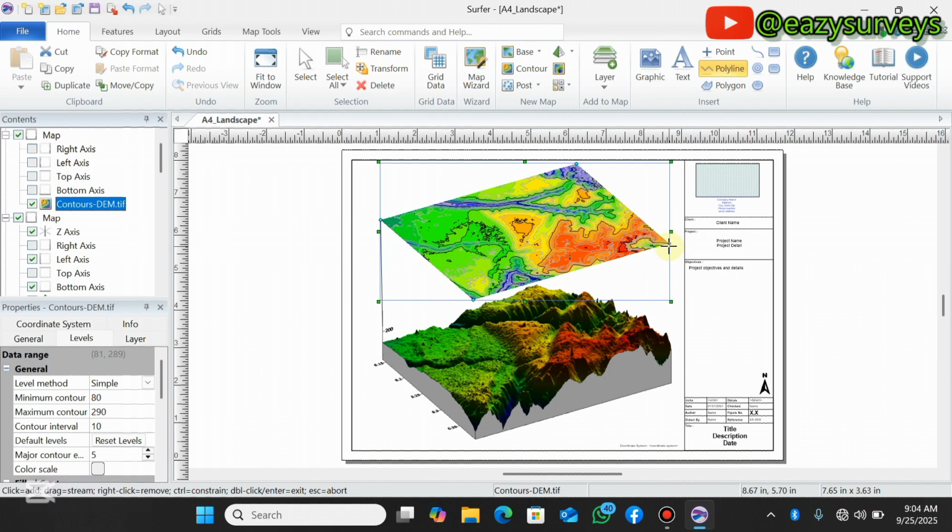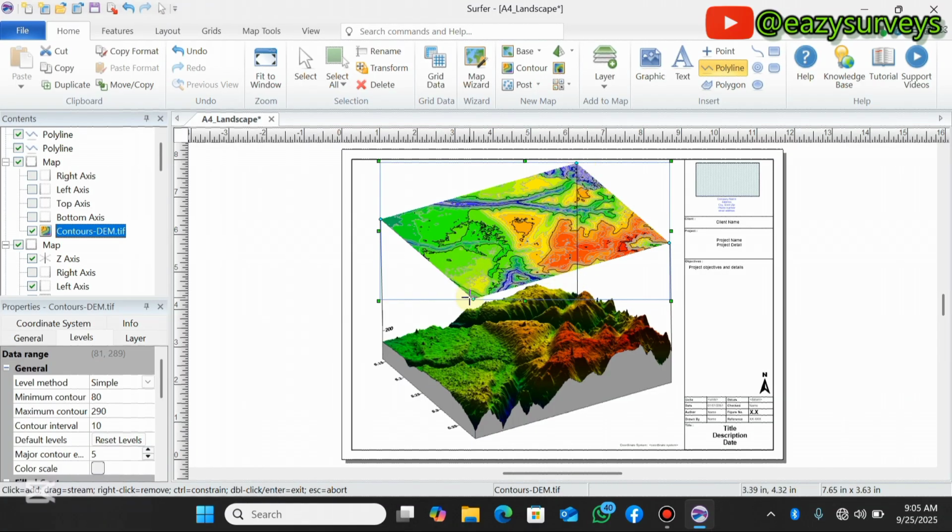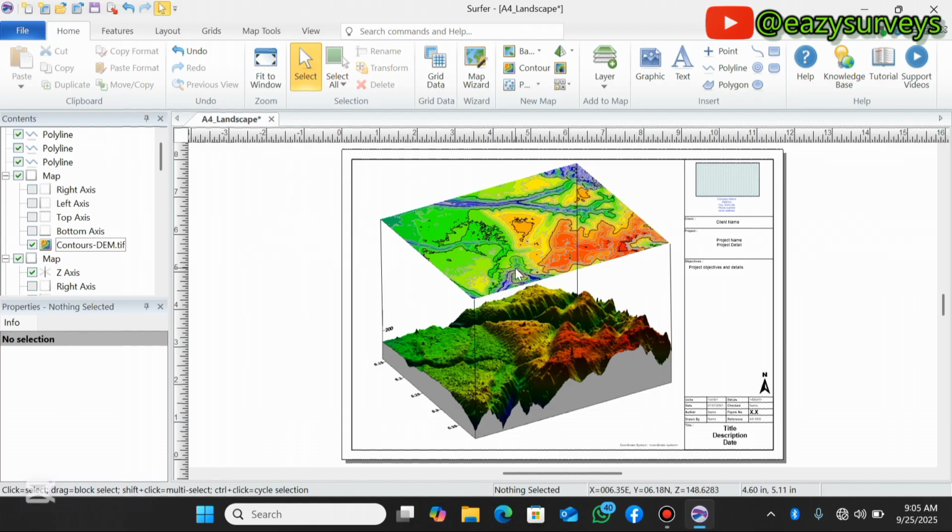The same way for this, you select this, then double click on this, then for the upper point, click on that, you draw it, then you join that. Then lastly, for this edge, select the edge, then let it be relative to this point, double click to exit the command. So you can now press escape to exit the polyline command. Then that is it. So we have successfully stacked this map together.